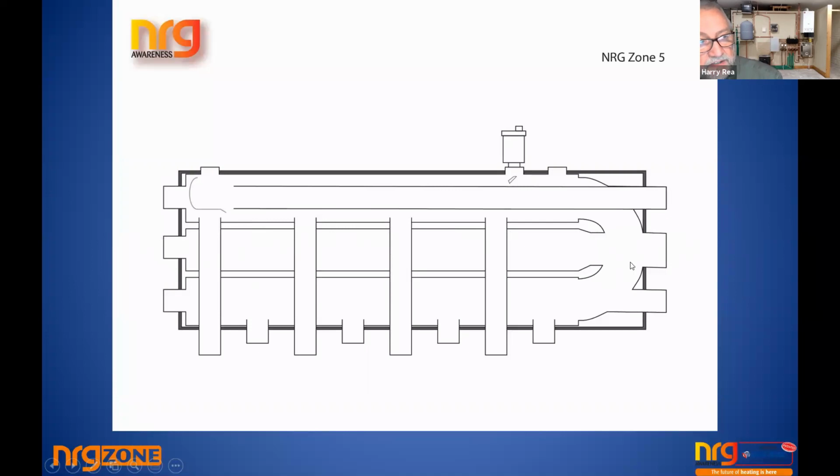If this is connected to what I'm going to class as the system's neutral point, everything is connected at this critical area. So the water coming in from a boiler here has a 2.5-inch pipe to get over to the perfectly open bypass and directly back to where it came from. If water comes in on this side, it hits the same baffle, but on the inside of the baffle, turns back on itself. And even though it's piped on the right-hand side, it flows from the left to the right in exactly the same path past all the open apertures for different zones, back around and down, and goes back to the boiler here.